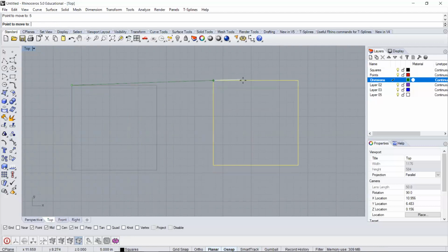And similar to when creating a line, I can see that I now have a 5-inch radius that goes around my starting point here. And I can just click to set where I want my square to be placed. I can also use this in conjunction with my ortho, and I can even do this mid-command. I can come down to the bottom of my screen and check the ortho toggle. And now I can lock my square movement in by 90-degree increments.